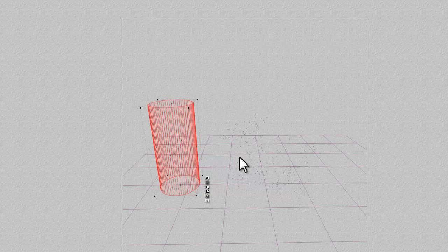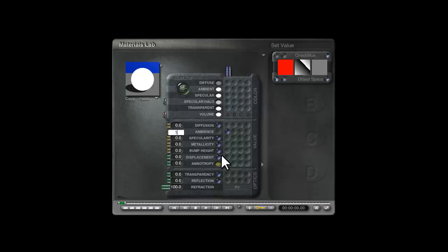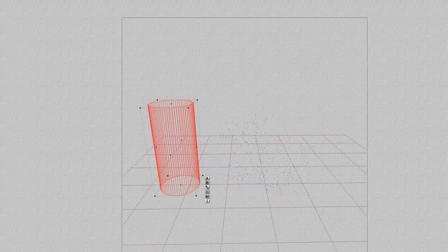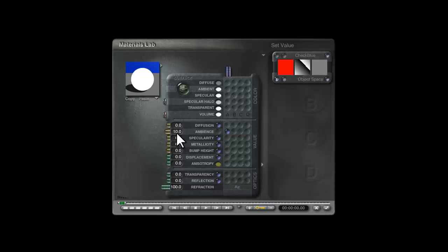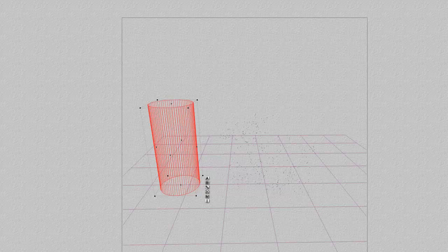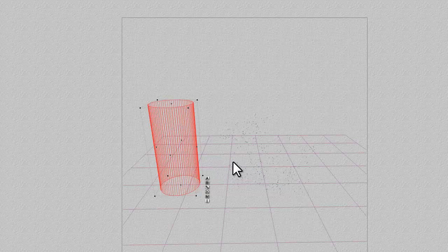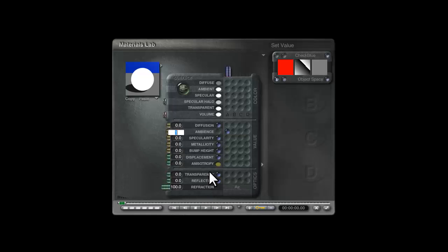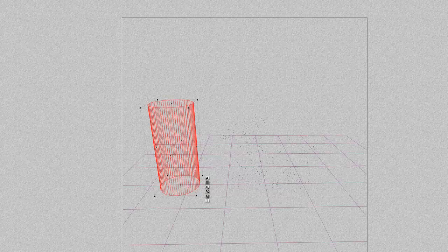So by combining these two effects together, we can rein it in somewhat. So now it's at a lower level, then we can go, say, try 10, and we've still got the option of going into the deep text editor to try and control it as well. If that's proving difficult, we'll try 1. So it's a matter of experimenting with the values. So you've got some output, but not too much output. So it's looking a bit white on the front of the dragon there. So we could try 0.5. So now you can see we've brought it into a range where we can control the output.